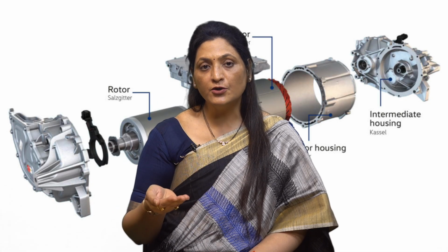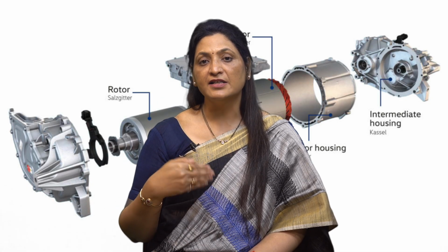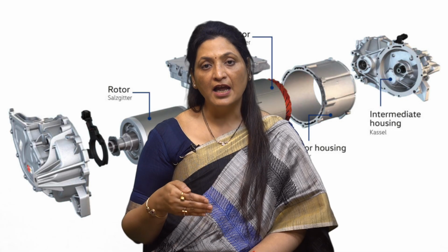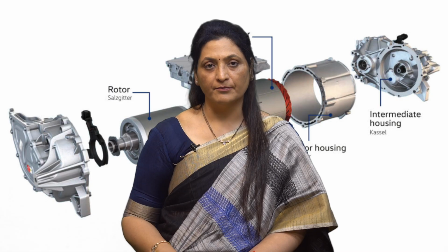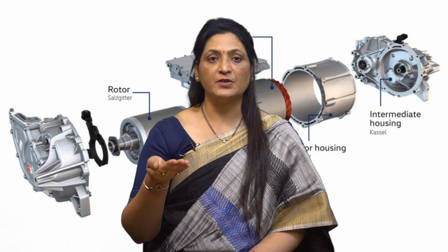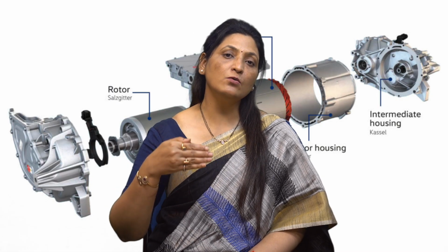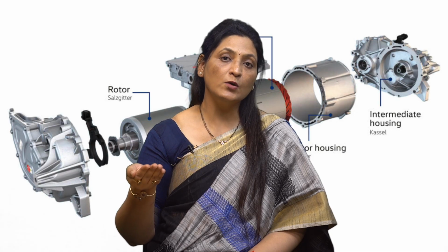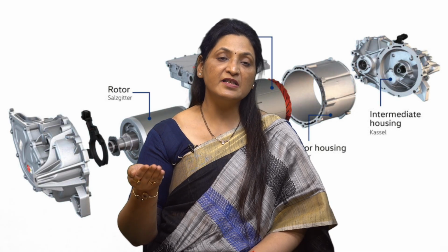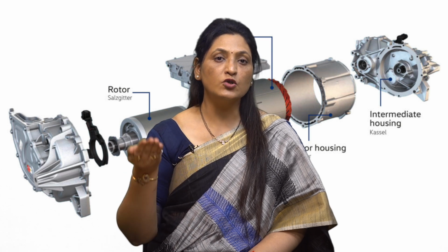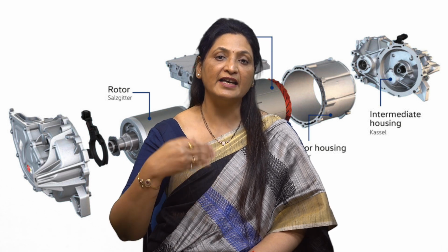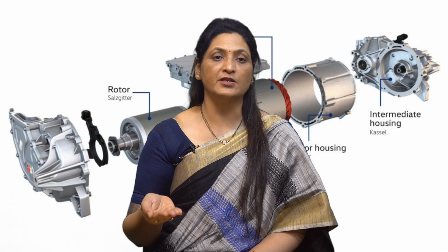Its power rating should be sufficient to handle situations where the motor is working at full load capacity and producing the most heat. The cooling capacity: the motor's ability to dissipate heat is equally important. The cooling system, like a fan or liquid cooling, needs to be effective to stop the motor from overheating and getting damaged during constant use.